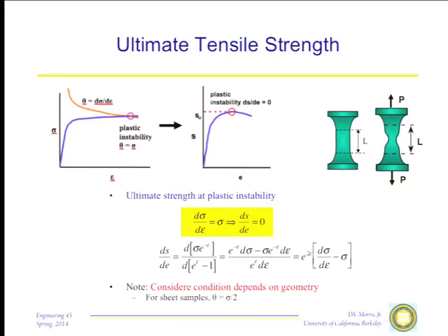On the true stress strain curve, we need two curves. We need both the stress and the work hardening rate, and we get plastic instability when the two hit. Now, I should warn you here, well, it's not that important, but as peripheral information: in deriving this Considere criterion, we did assume that the area decreased in an equiaxed manner, and that's true for a cylindrical bar or a bar that's equiaxed in its various dimensions.